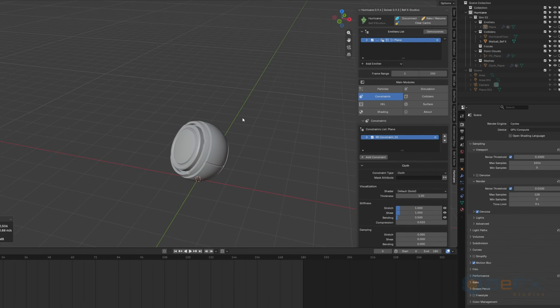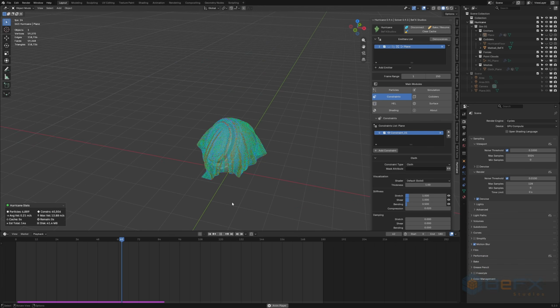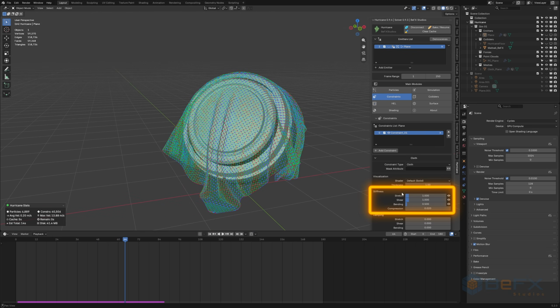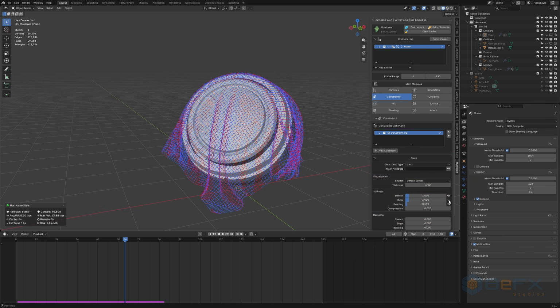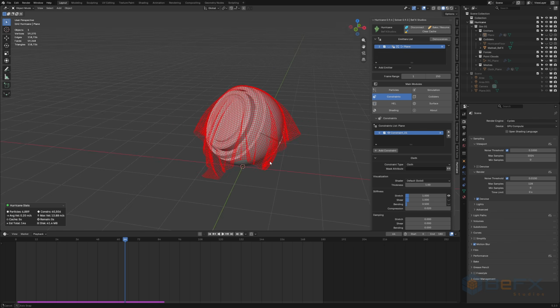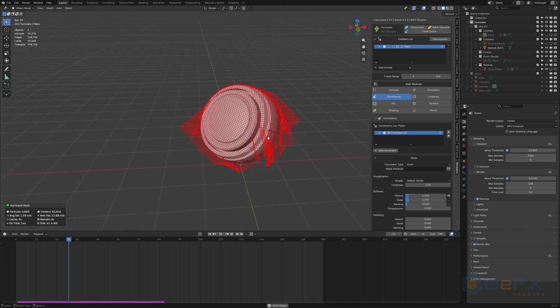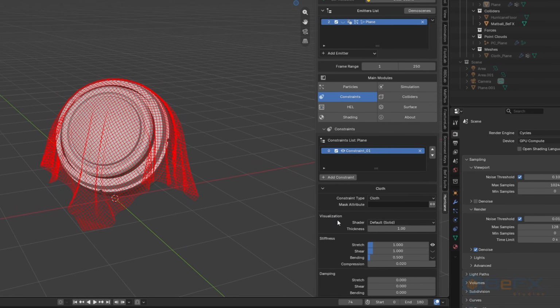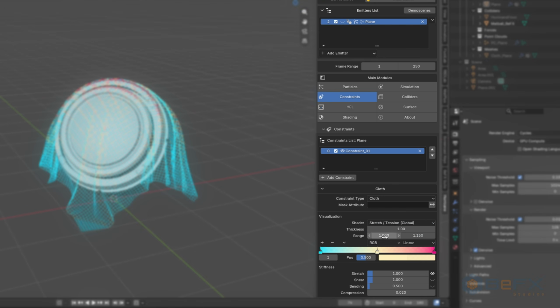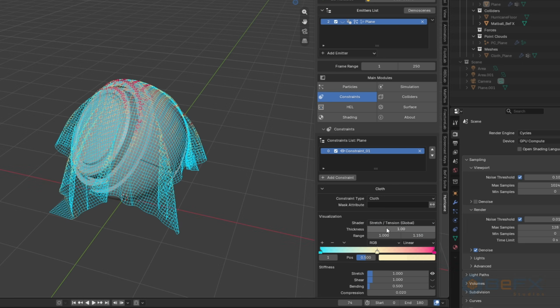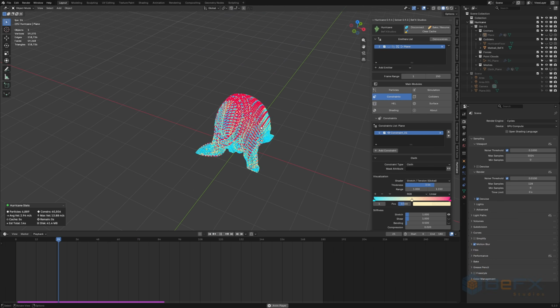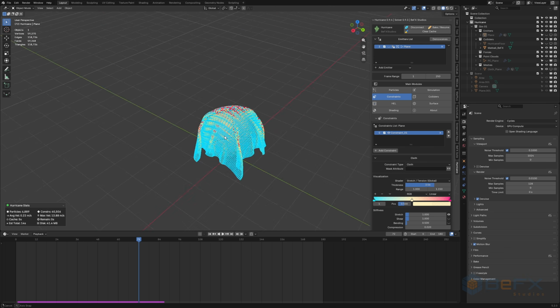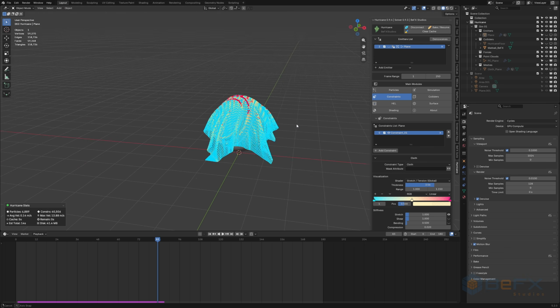We have four main control types in our cloth constraints: stretch, shear, bending, and compression. We will explore these controls in detail later, but for now, we'll simply tweak a few values to observe the different behaviors. First, let's enable constraint visualization to understand exactly what each parameter controls. We hide the mesh display and enable constraint rendering. Upon playback, we can observe a network of lines interconnecting the geometry. These lines act like tiny rubber bands holding vertices together.